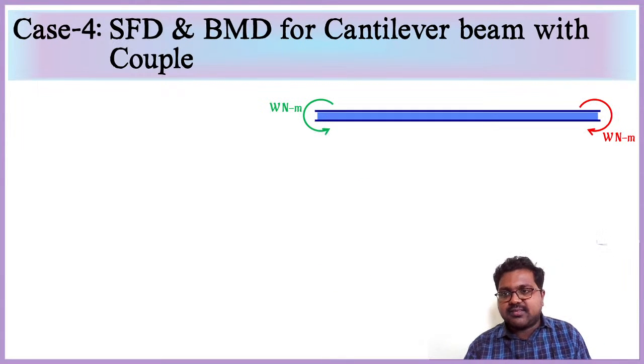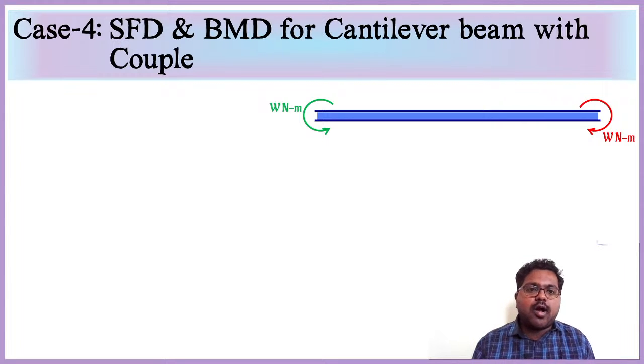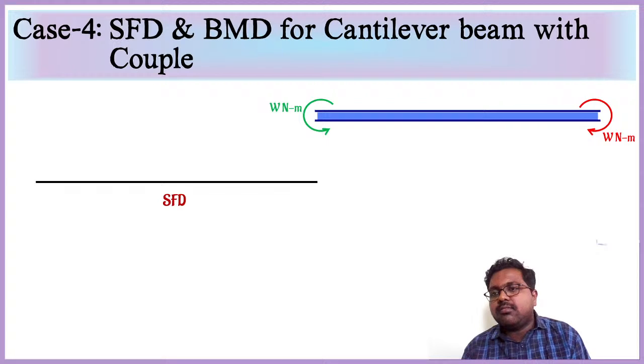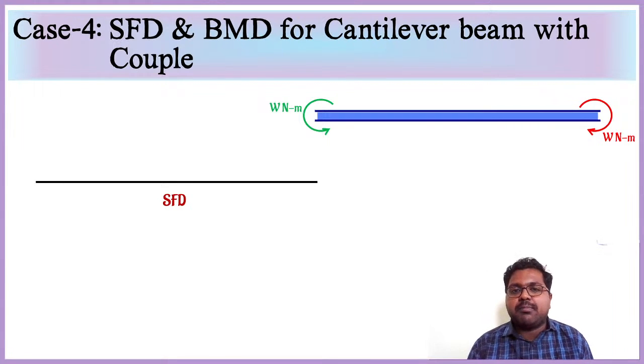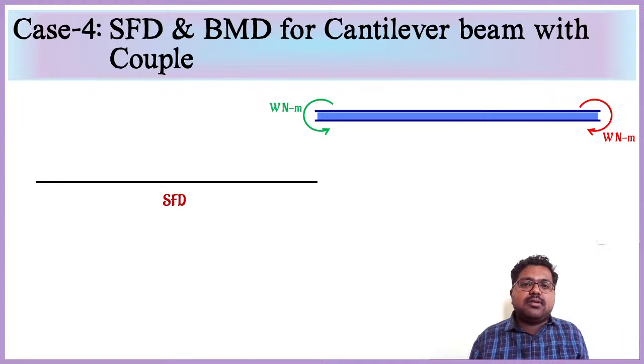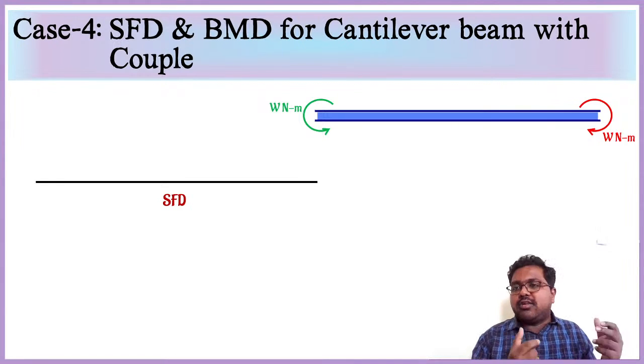So we'll get a figure like this. If we want to draw the shear force diagram, there are no normal forces or vertical forces on the beam. So the shear force diagram is just a baseline. Nothing is there to draw.